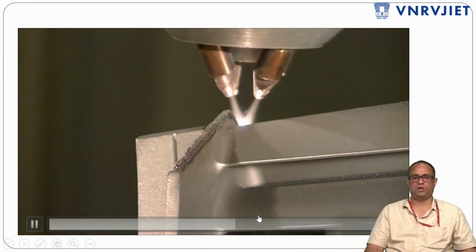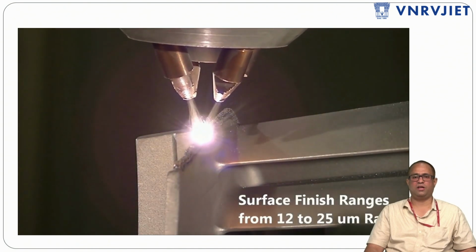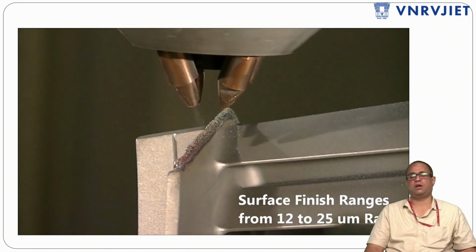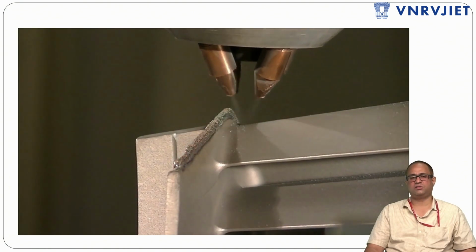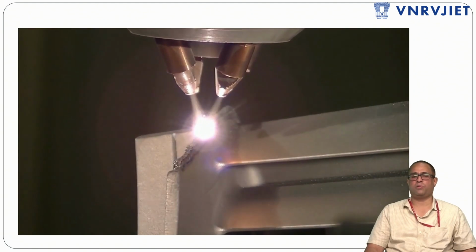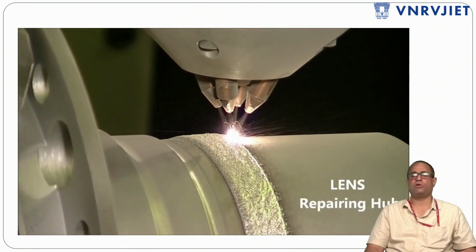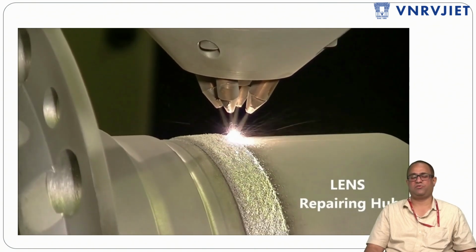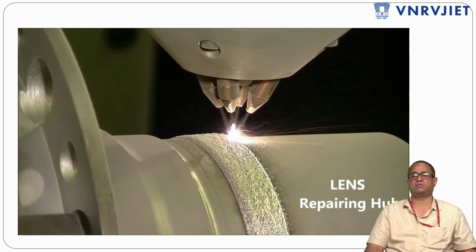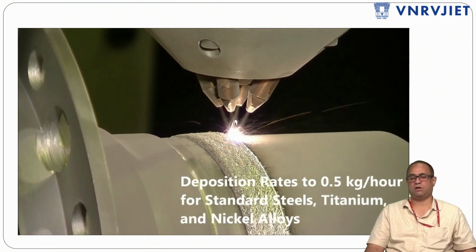You can see how it is going to be deposited: powder and the gas, and in between a laser spot. And the specialty of this laser engineered net shaping is that it is able to add to parts, wherever the parts are subjected to wear. If the parts are worn, we are able to add layers, whereas with the other techniques, it is not at all possible. So this is an exclusive specialty of this LENS.